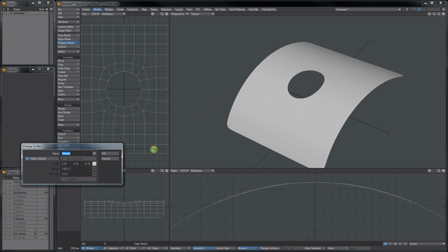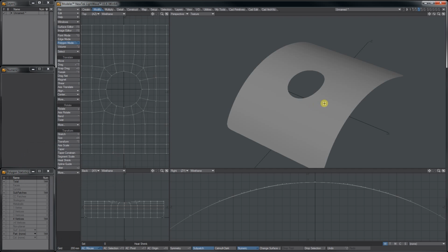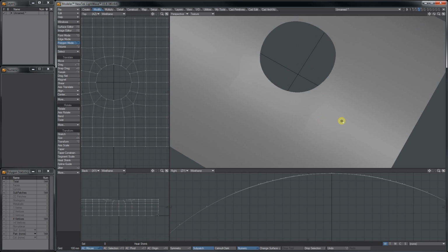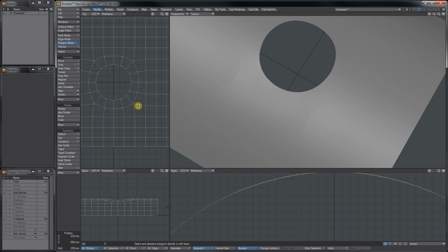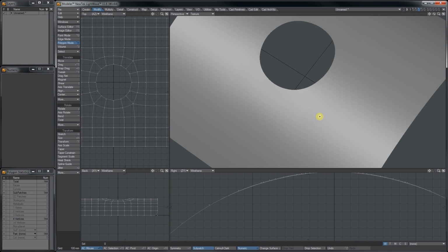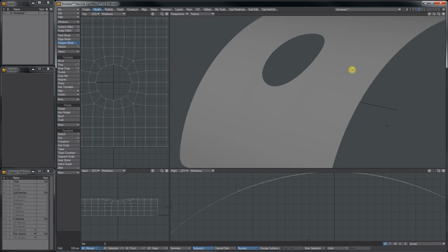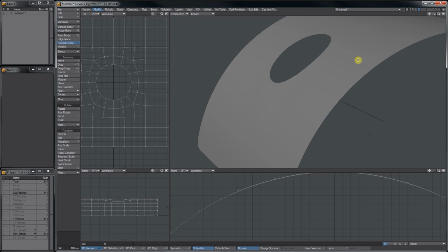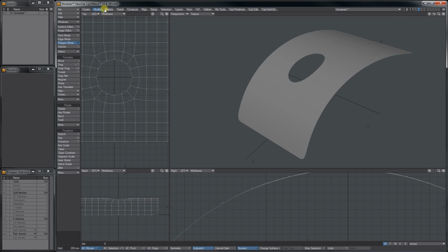So at this point I'm going to go ahead and create a surface, hitting the Q key. I'm going to name it glossy, and we'll set it to 70 on diffuse, 30 on specular, and smoothing. It just allows us to see with reflections how we're doing. Now you'll see these little pinch marks, and those don't appear to show up in layout, so I think we're okay, but they are there where you get the polygons around the single point, 5 polys around a single point. You can barely see the dents holding it in certain areas, but overall not too bad.